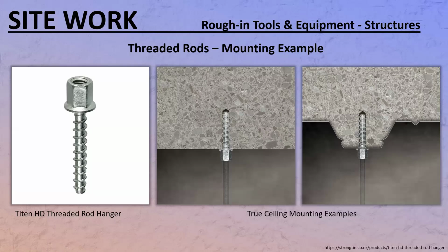So if you see that kind of spray over the ceiling, then you have to go and mess with that to clear it out of the way, and then the particles get airborne and you breathe them. So if there's MMF, then you need to have proper PPE. And sometimes you have to follow certain procedures, like spraying some water on it so the particles don't get airborne and things like that.